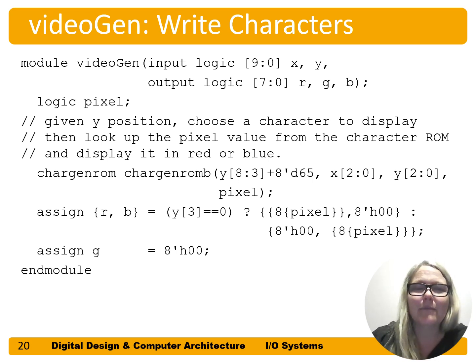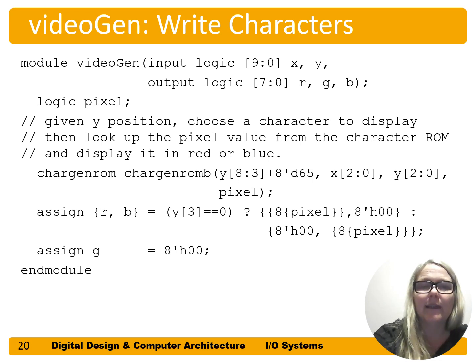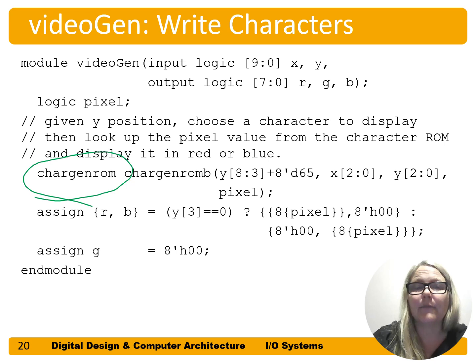So this has a character generation ROM. It has a ROM here that is going to basically give us characters. It's also called a pixel map for each character. And we can feed in some value. It's basically going to repeat every certain value on Y. And so we just feed in the bottom values of Y, so it'll repeat every basically 8 pixels.